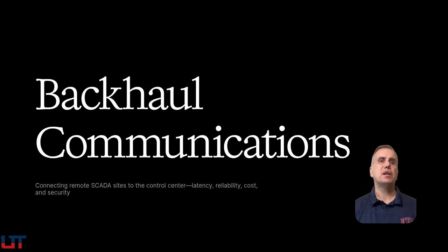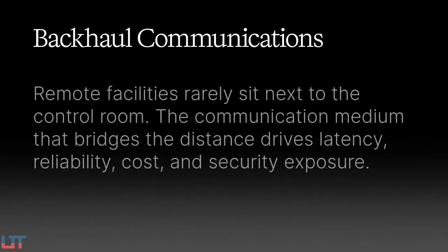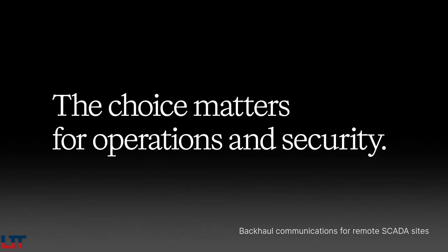In this video, we want to cover backhaul communications, which are the network paths that connect remote SCADA sites to a central control center. Pipelines, substations, pump stations, lift stations, and water treatment facilities are almost never co-located with the control room that monitors them. The communication medium that bridges that geographic distance determines your latency, your reliability, cost, and security exposure. The choice matters for both operations and security.